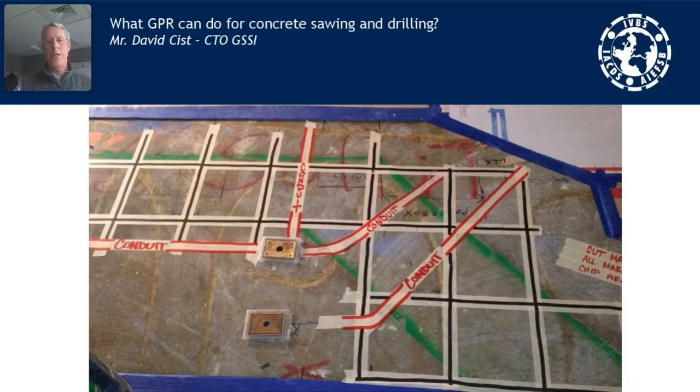This is also a really good example. You see the green trench line lines up exactly with one of the rebars on the bottom left. And that would be an example where if you could, you'd probably want to move your trench just a little bit to avoid lining up so carefully with that rebar. You would shorten the life of your saw if you had to cut through a long line of rebar, but you can also bind the saw and create trouble for yourself and for anyone else.